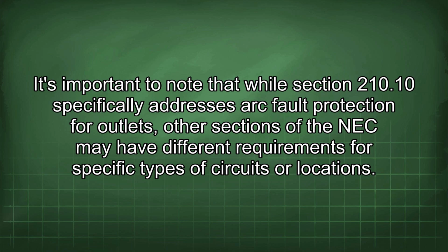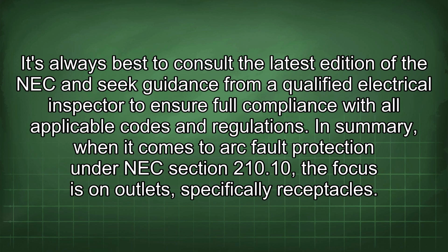It's important to note that while Section 210.10 specifically addresses arc fault protection for outlets, other sections of the NEC may have different requirements for specific types of circuits or locations. It's always best to consult the latest edition of the NEC and seek guidance from a qualified electrical inspector to ensure full compliance with all applicable codes and regulations.